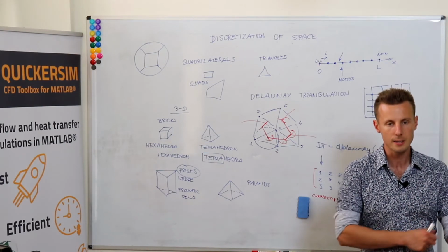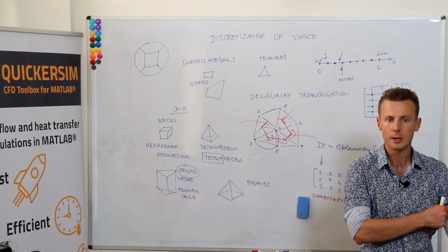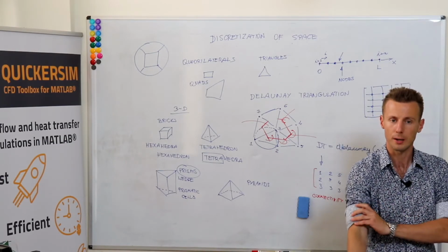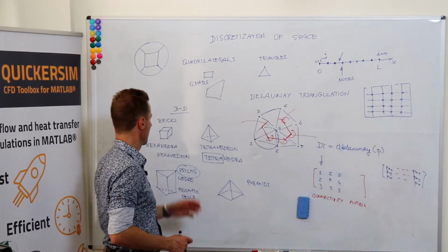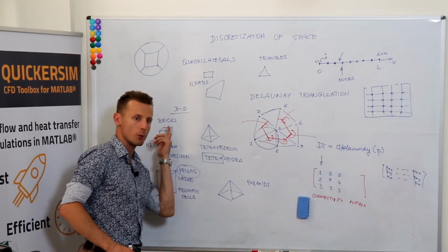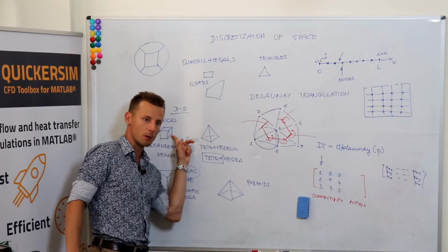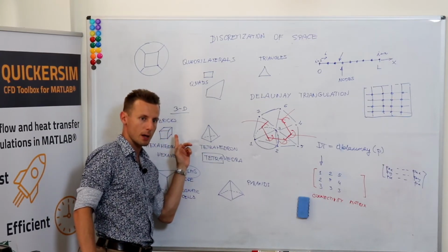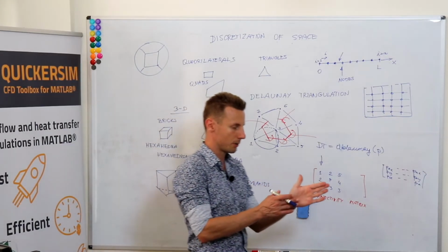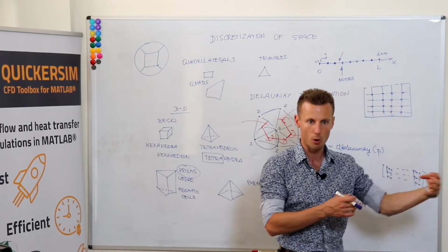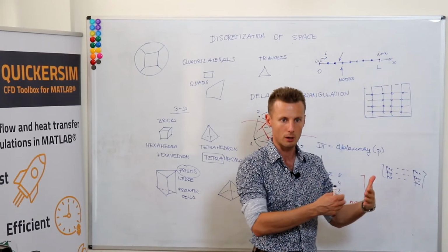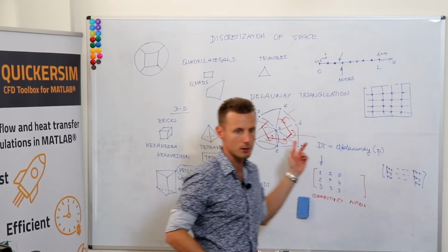Anyway, hexahedra are a very nice type of cells for the finite volume method, because generally well-built hexahedra mean that you should be close to 90 degree angles at the walls. Then if you need to calculate the fluxes through the walls and everything is perpendicular, you've got nice structured meshes.